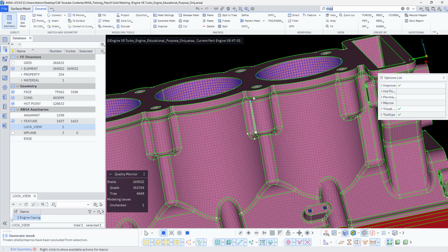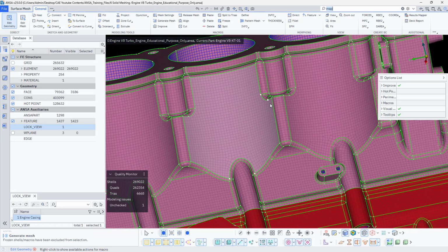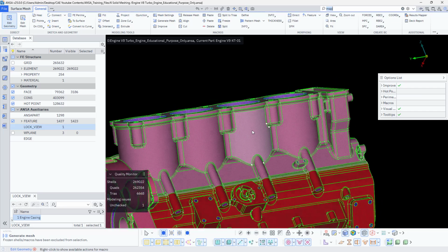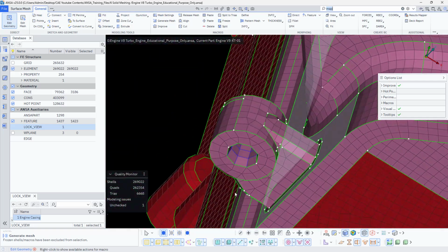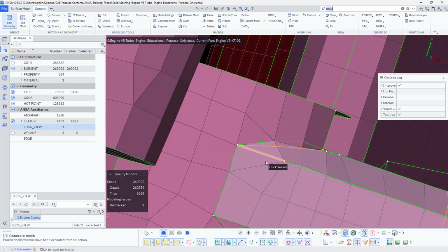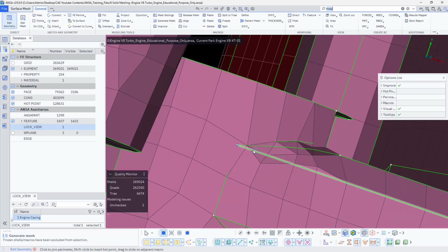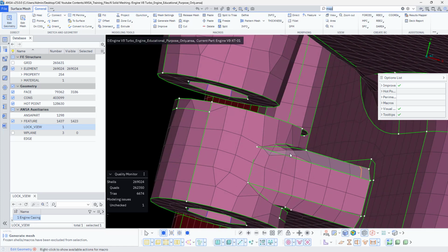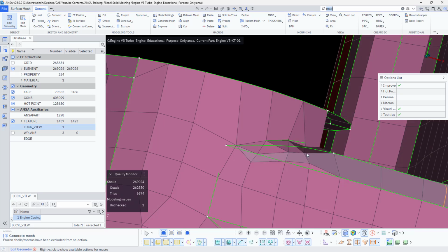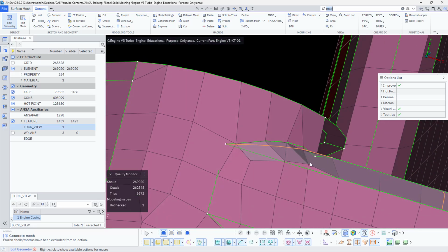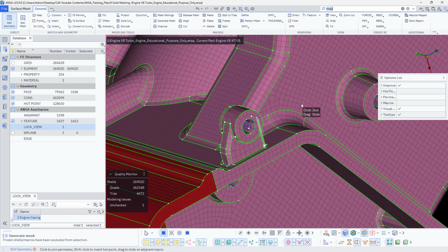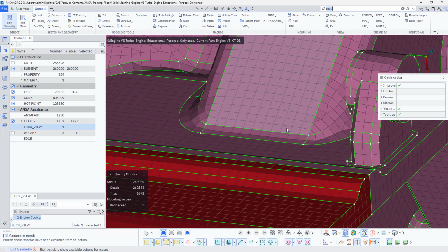Let's say sometimes you have suppressed some regions. Let's find some regions. Now we'll closely monitor how it has meshed. Okay, at this region you could see, you can even bring back these features so that you can have this mesh distributed, and once you release the mesh, it will be getting the model, and you can refine it, or else if you don't want it, you can click it back so that you can have this kind of mesh. Okay, so it depends on you and the requirement,